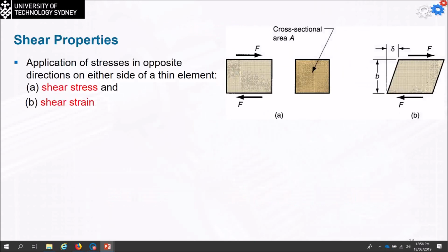The other type is what we call the shear properties. So we said that shear is sliding in the material and having the cutting. So that's what will happen. I can add forces in opposite directions. This will be the original cross-sectional area. Again, to have a certain sliding in the material, which is the shear strain. Then simply, I can calculate the value of the shear stress of this part. Same thing, the force divided by, in this case, not the cross-sectional area, but the shear area.